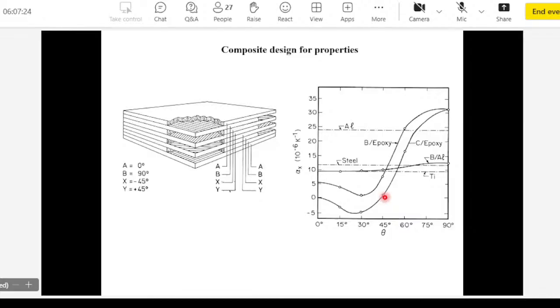Glass and epoxy have very similar density values. So by changing the amount of glass fiber, you don't change the density. The impact energy or toughness drops as you add more fiber because glass is more brittle. Let's put it that way.